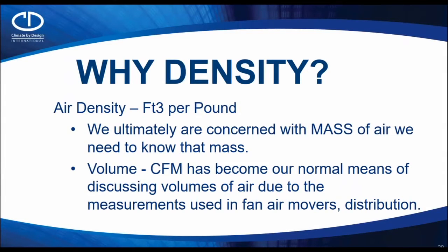Why are we concerned with density? Because ultimately we want to know the mass of the air volume, and we need to know that mass to run our calculations. We generally know the CFM of a system. That's become our normal means of discussing volumes because we're using fan air movers and distribution, ductwork, and that sort of thing. So our normal conversation is around CFM. But in order to understand the heat and dehumidification required, we really need to understand the mass of the air.